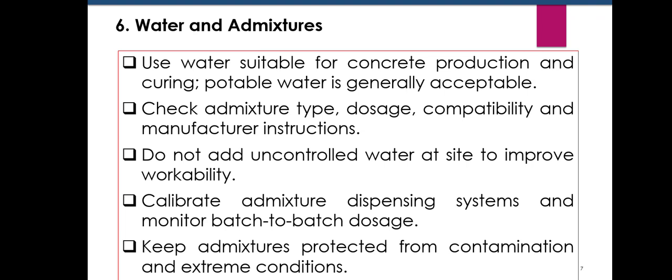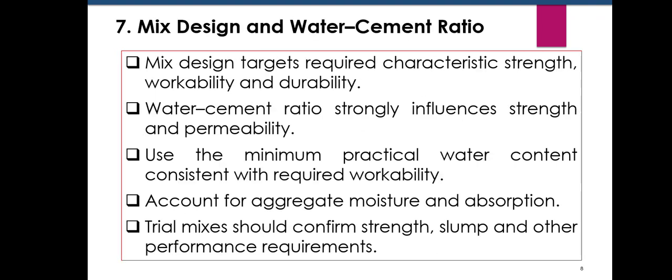One very important rule is do not add uncontrolled water simply to improve the workability. Adding extra water can increase the water cement ratio and reduce the strength and durability of the concrete. Admixture dispensing system should be calibrated and the dosage should be monitored for every batch of the concrete mix.